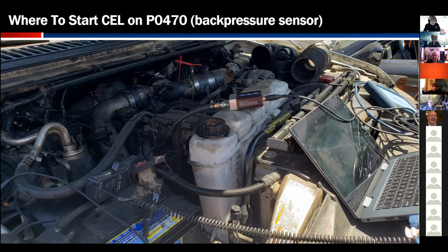I mean, geez, guys, I've got three different Pico boxes. I've got a 4-channel 3000 scope, a 4-channel 4000 scope, an 8-channel 4000 series. But if I open a PicoScope 6 beta, a PicoScope 6, and PicoScope 7, I can have 16 channels on my screen at once. And that is some whacked out, geeky stuff. But the point I'm getting at here is the more data, the better. But in this case, I can at least get to look at pulses in the crankcase during the cranking relative compression test. And when I did the test, here were the results.